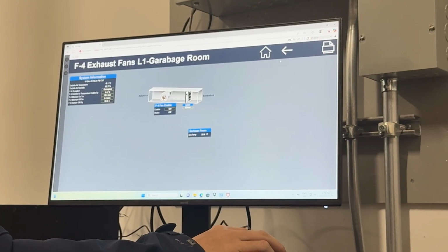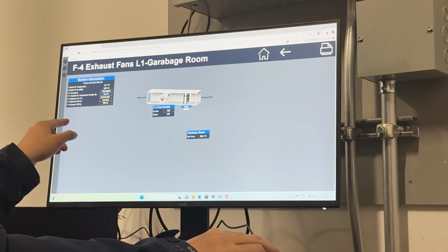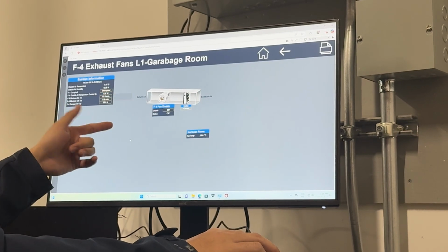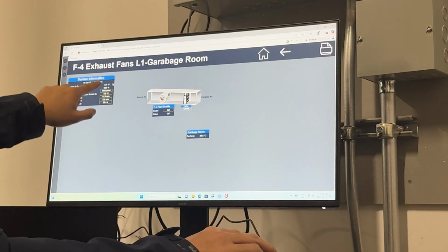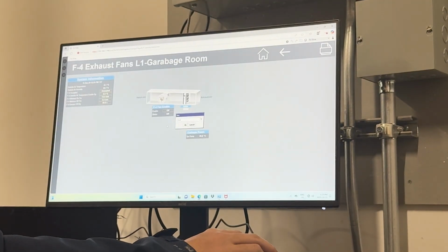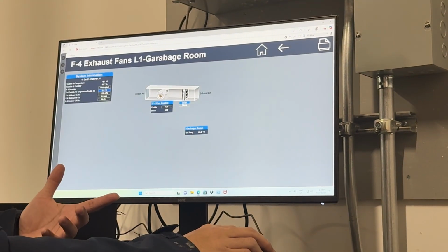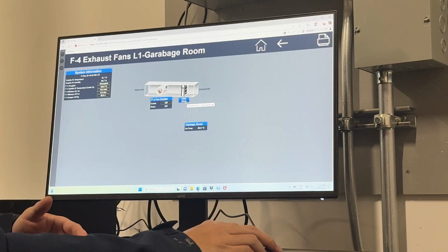That's for the garbage room, when the outside temperature is below 5. Below 5, but it's adjustable, right? Yeah. So right now, for example, it's -10. I can change this to -20. If I change this to -20, I should see this open.